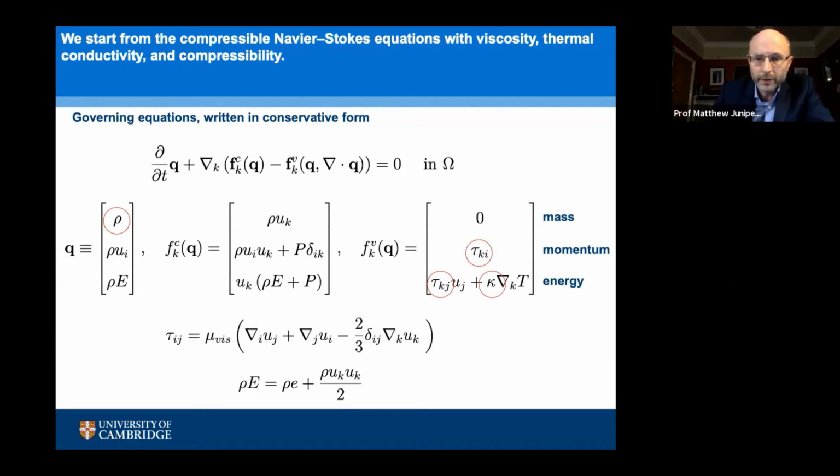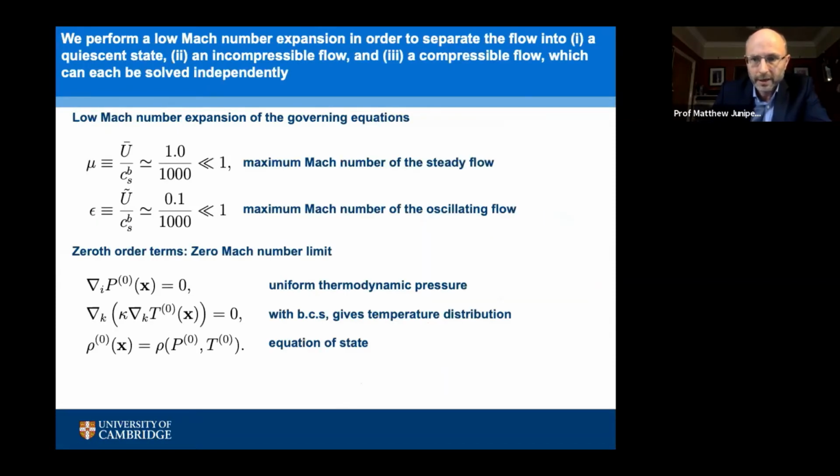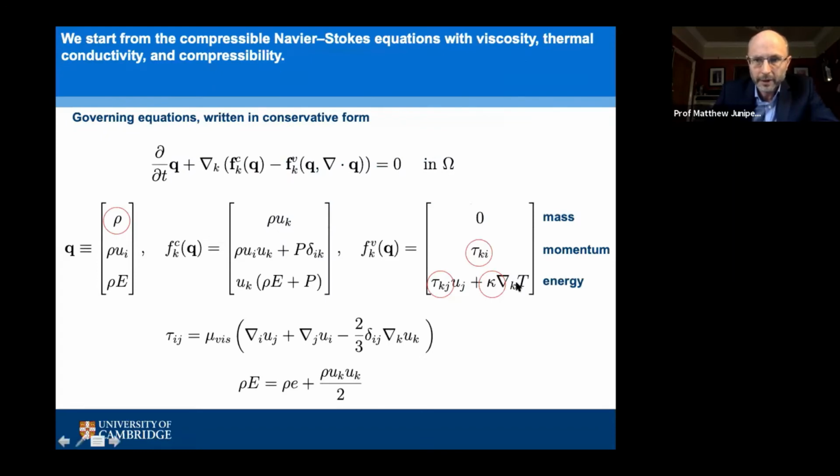And because you get temperature differences in a sound wave, you get temperature gradients, and then you get thermal conduction across temperature gradients. That leads to an increase in entropy, and any increase in entropy is just another way of saying that mechanical energy has been dissipated into thermal energy. In other words, you've lost mechanical energy, you've damped the acoustics. And that can be very influential.